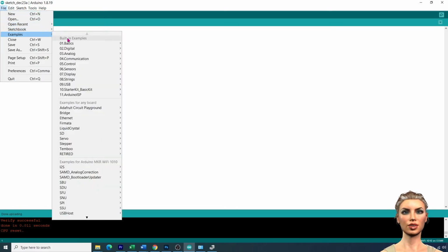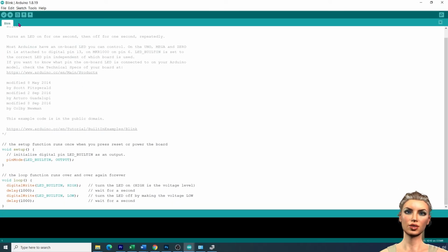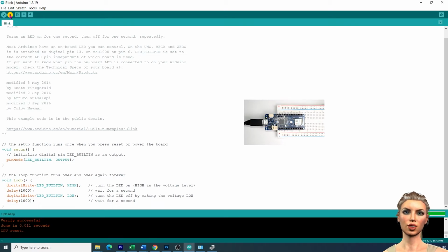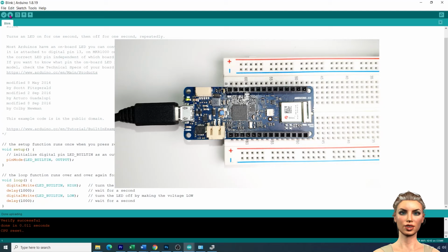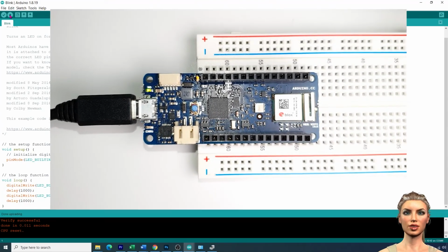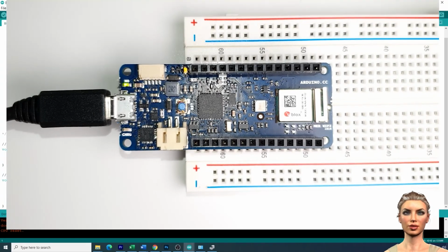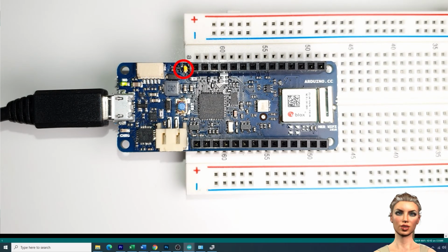We make sure that we have our Blink program open on the IDE working area and we simply press the Upload button that is in the upper left part of the screen, which has a small arrow pointing to the right. At that moment the IDE will begin to transfer the program to our board, and at the bottom of the screen we will see information about the memory required by our program on the board, as well as the total memory available. If all goes well, a message will appear indicating that the upload process has finished correctly.